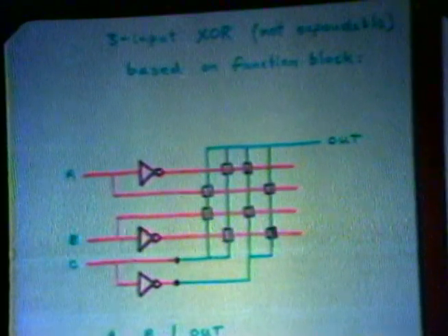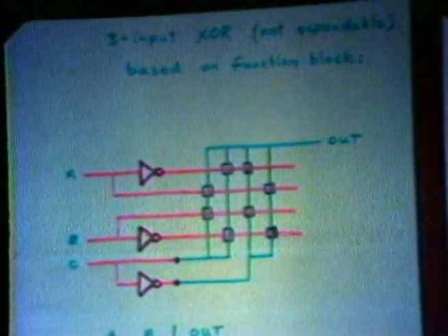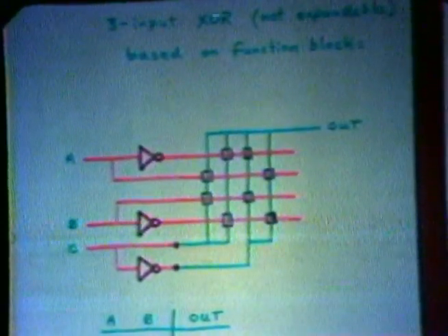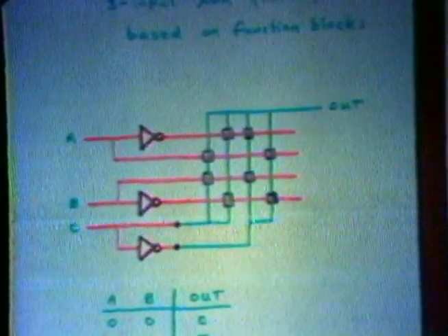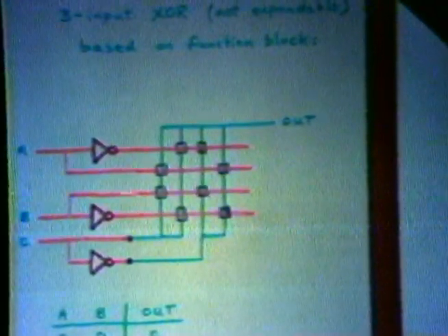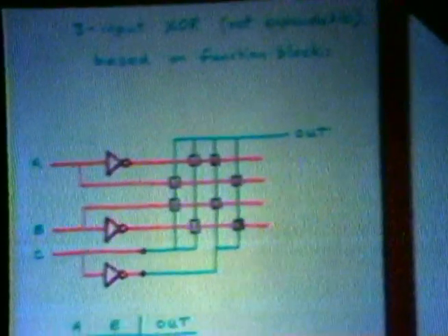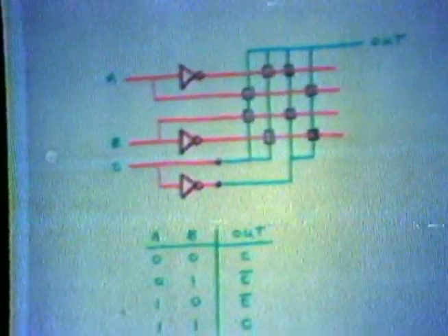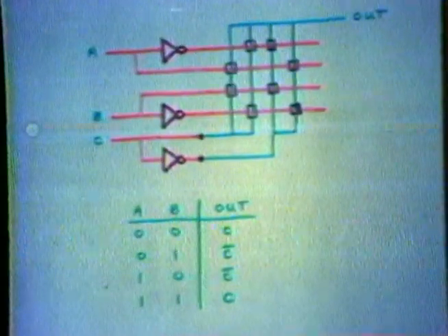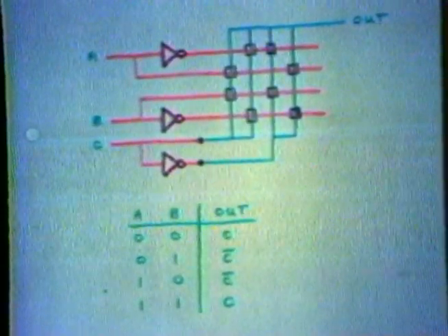Is your game to draw inverters just sort of arbitrarily like that wherever you go? It seems to me that when you come to actually put them in, you have a certain amount of trouble, don't you? You're right. This isn't really a valid solution because I asked for a stick diagram, and this isn't fully converted to sticks. This is mixed notation. Well, my question was a little bit more subtle than that. Is it in fact okay to play this game?